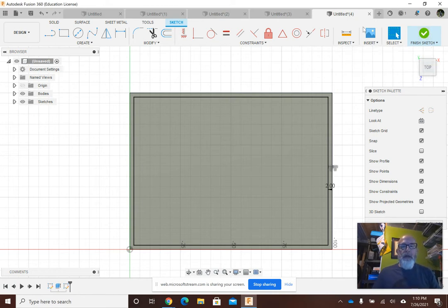Just thought of this. Tried to draw another rectangle here, but I would have had to determine what the starting point is and where the ending point would be. I would know the dimensions because this is 100 millimeters, so I would have known it's 96 millimeters. But am I starting it 2 millimeters in? I could draw a construction line of 2 millimeters to give me a starting point. So draw one across 2 millimeters up and 2 millimeters across, or do a little construction rectangle, which is a 2 by 2, and it would have given me a starting point. The offset's a lot easier.